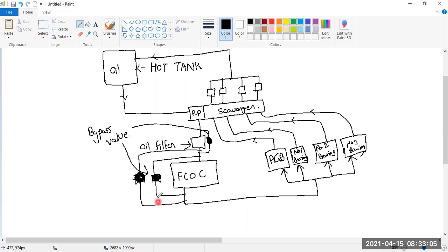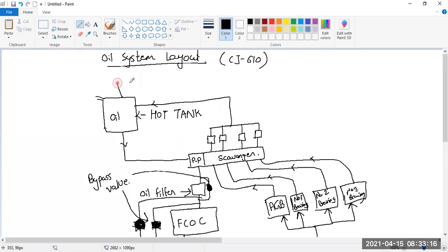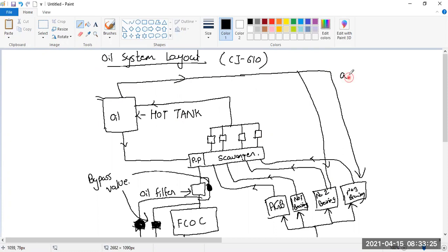Okay. Next thing, what I told you is there should be air pressure here in the oil tank. I told you 5 psi pressure, right? So what the manufacturer will do is ensure that the same pressure is available in your bearing compartments. This is air pressure we are talking about. The same pressure is available in all your bearing compartments. This is called a breather system. We just studied in the bearing compartment that the pressure port is there from where the pressurized air is coming. This is the breather port. Pressurized air is coming, and the same pressure is also available in the oil tank. So there should be the same pressure, then only the oil will go further.